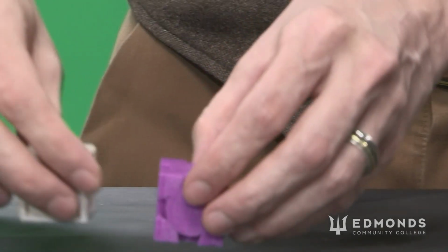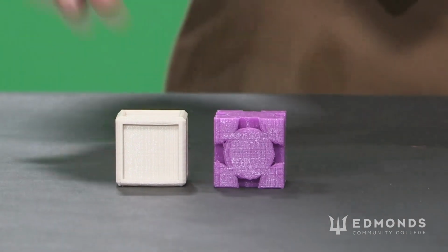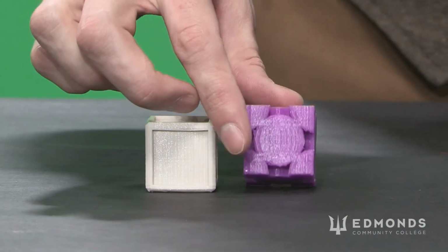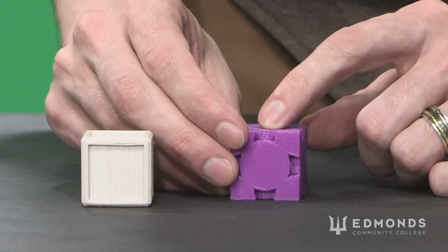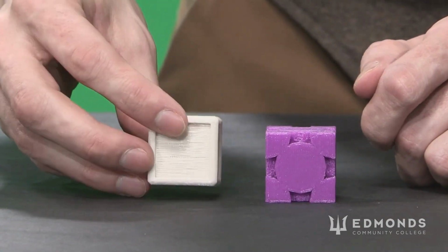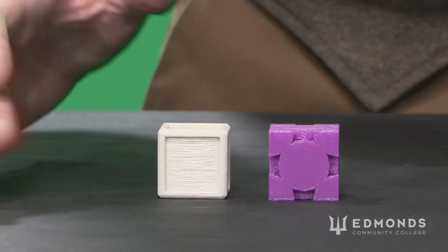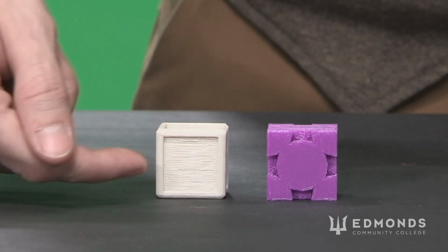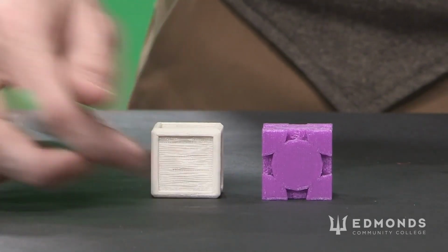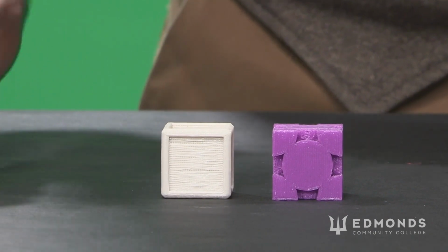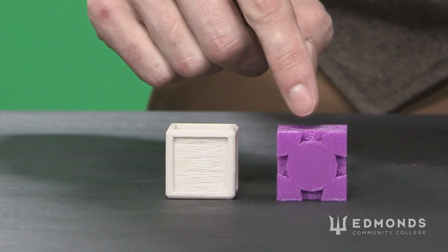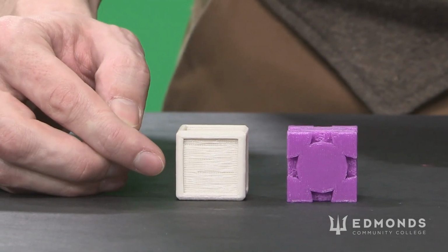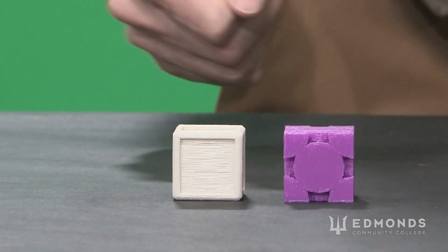We have here another set of examples of the kind of errors we have to deal with when we're choosing what settings and what properties we want to optimize for in our printing. Underneath these edges, you can see those overhang errors we talked about before. And underneath this edge, you see what's called a bridging error. This is very similar to an overhang error, but you can see this layer is stretched between two support posts, two supported regions, and yet it's still sagged down even though it was under tension. So in this case, we may need supports in order to solve that problem, whereas in this case, changing the rate and temperature of our extrusion may solve the problem instead.